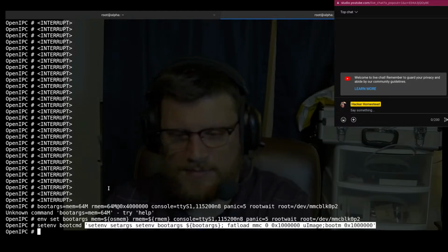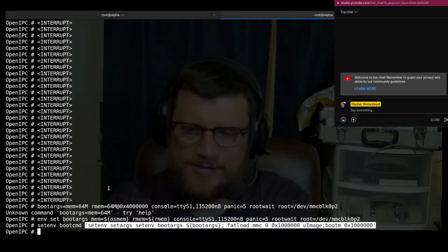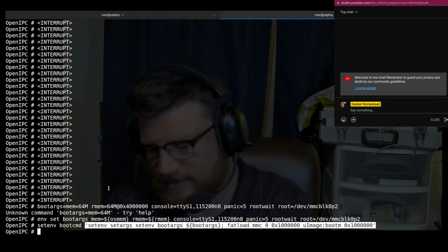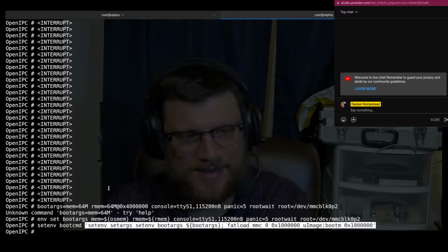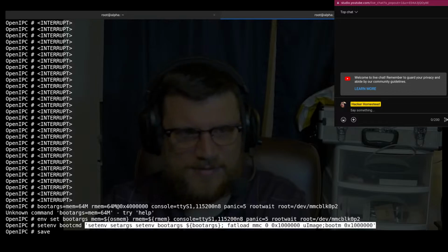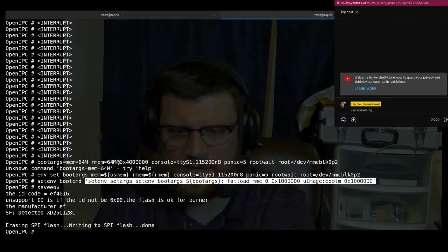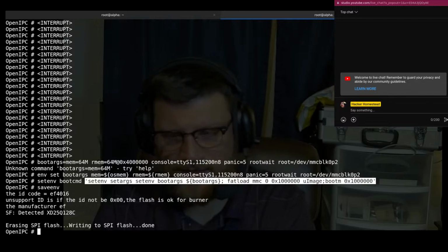And that will keep giving you the feeling that you succeeded because your thing successfully booted. However, again, you didn't save them, so it'll exit before you get the chance. So now we're going to do a saveenv. Okay. And in theory, it's now written to the flash, and I think we do a reset. Or I can say boot command.